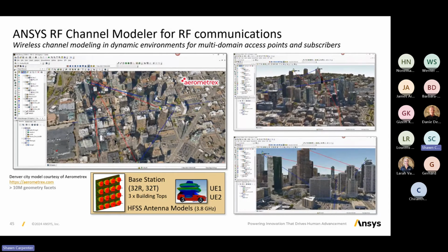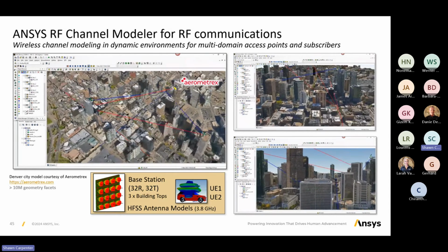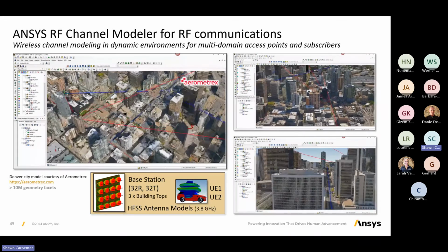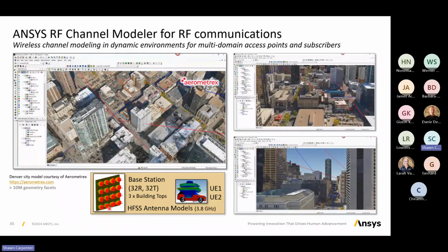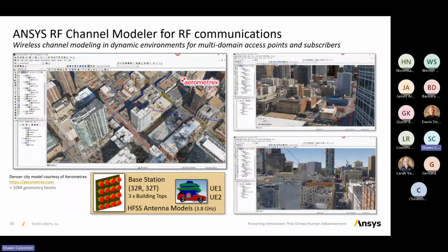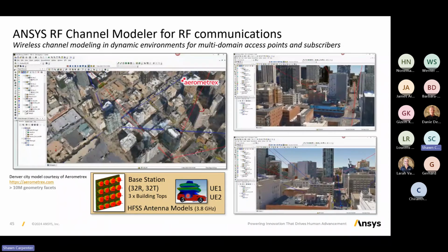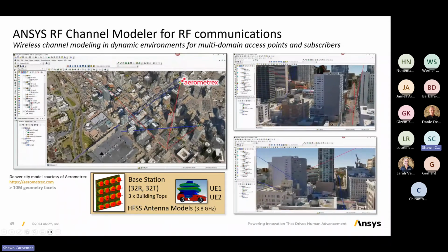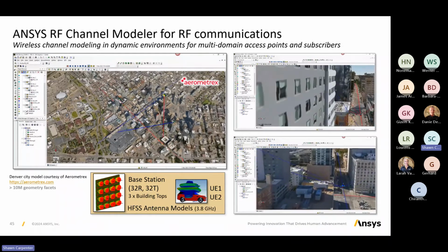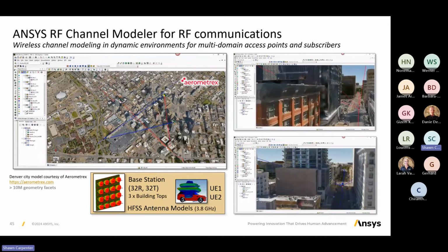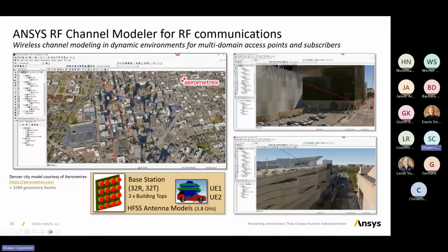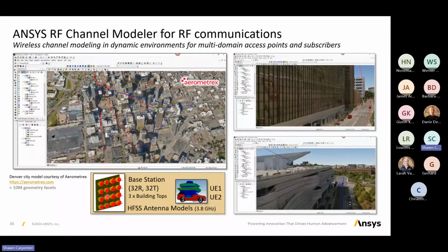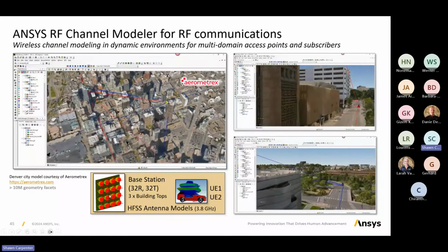This is our system toolkit mission simulation software that has models of 3 5G base stations, each with 32 ports. You can see the model for that antenna. We have the installed antennas. We've got a shark fin antenna here on a couple of Range Rovers that are driving through the environment. And then we're modeling the connectivity from our vehicle to each element of each array. So this is 192 channels that we're simulating.